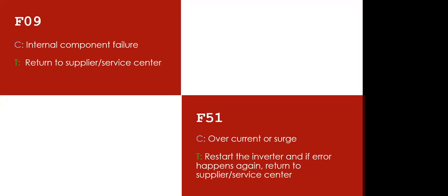The burst soft start fail is a particular section of the DC to DC switching on the inverter. It majorly affects either the IGBT on the main board, or the MOSFET on the main board. So this fault is particular to switching when the inverter wants to start up.